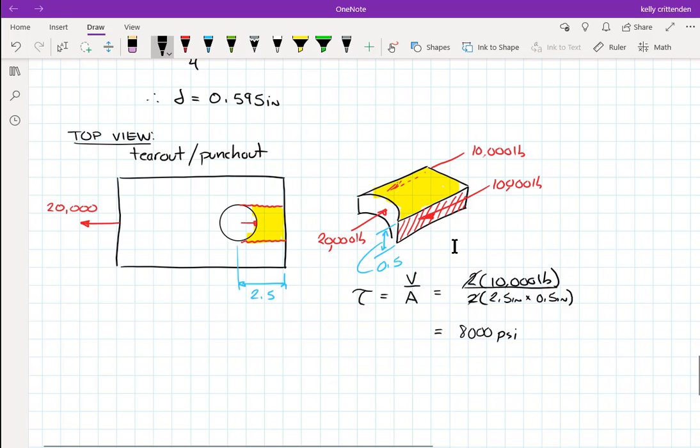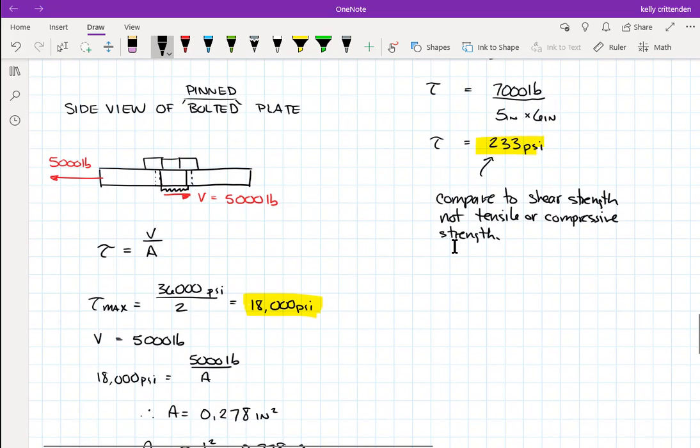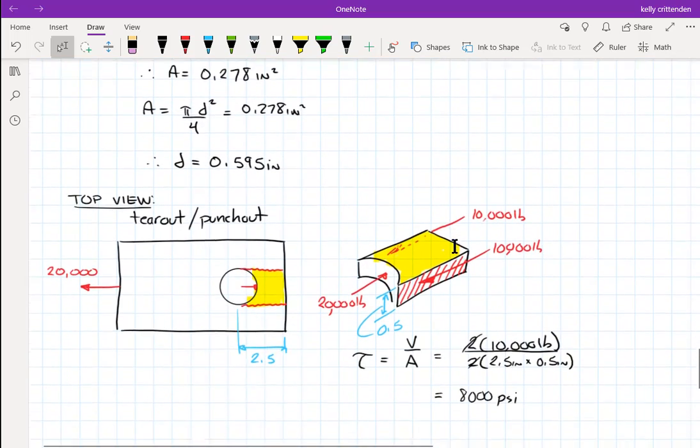All right. I think that gets us the basics of shear stress and axial stress. Bearing stress is a part of axial stress. You've got some web work problems that are going to re-emphasize each of these. Particularly, a lot of web work problems are going to look at this. They're going to call this a pin joint type thing. It's going to be two plates. We didn't do a lot of pieces all on the same plate, but I think there's one web work where you might calculate 3 or 4 of these modes of failure all on the same piece and figure out which one is the worst case, which is getting into interesting things.